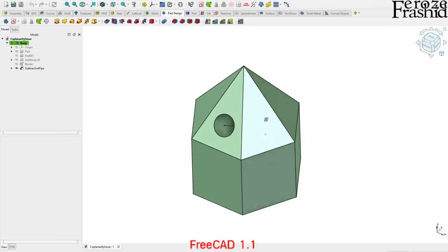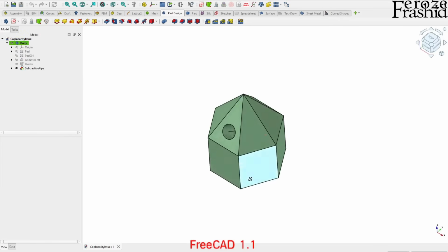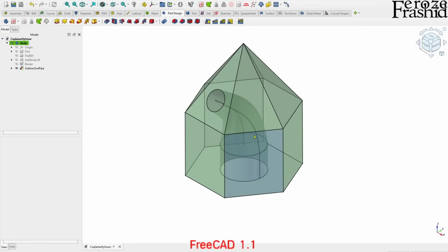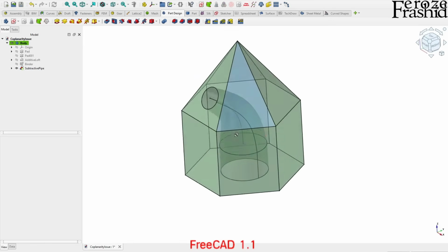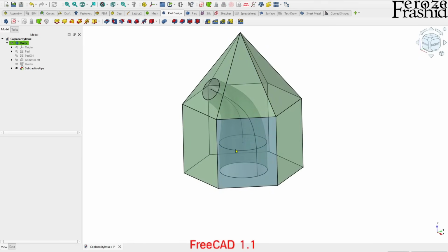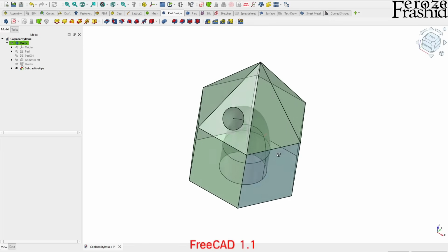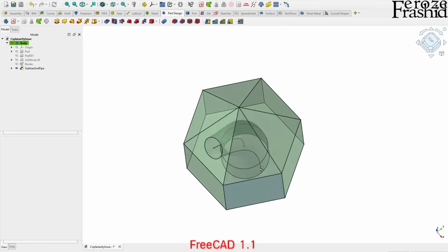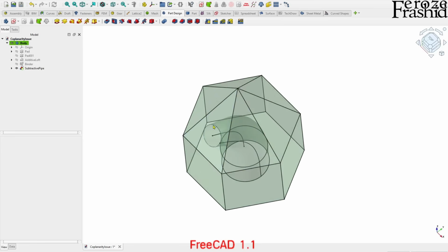So my workaround, the recommended workaround, is to work with a slice of it. All right, let me explain a little bit more. Here, when I'm trying to rotate it and then polar array it, this lower part is where this overlapping is happening. The coplanarity, the plane on top of another plane, is happening. So we can get away with it if we only use this slice of it, this little piece. We just build that and then polar array that one.